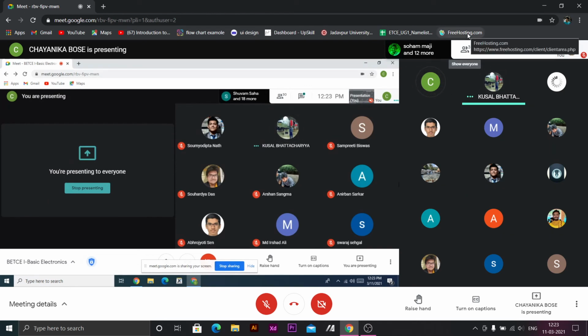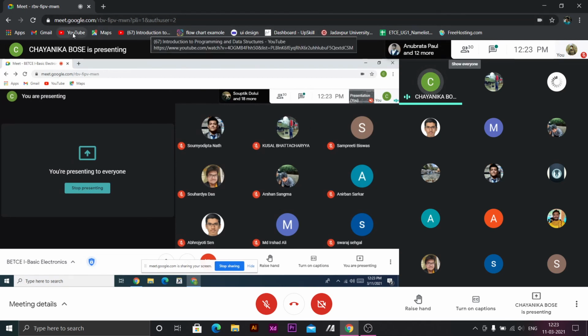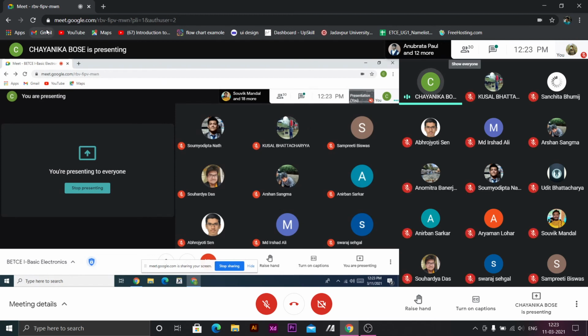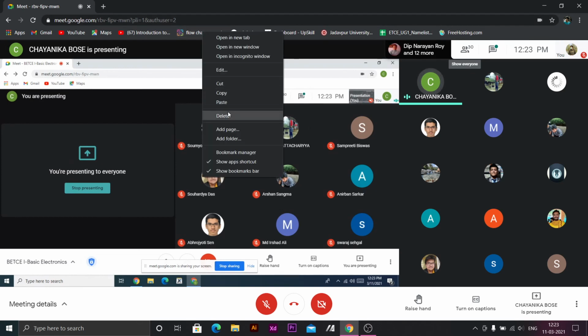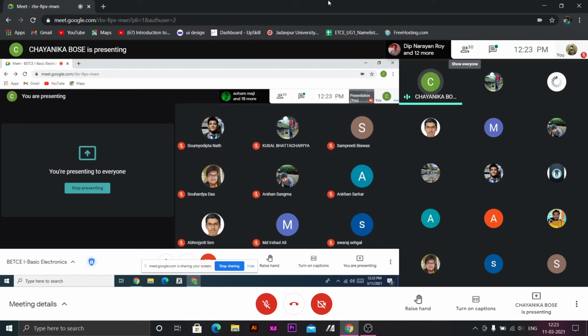না, কাট অফ হবে না। কাট অফ মানে you are giving some non-zero base current। তার মানে একটা certain 100 মাইক্রোঅ্যাম্প বেস কারেন্ট মানে your base emitter junction definitely forward biased। If it is cut off, your IB will be nominal, না? তার মানে base emitter junction is forward biased. So again, cut-off region is ruled out.